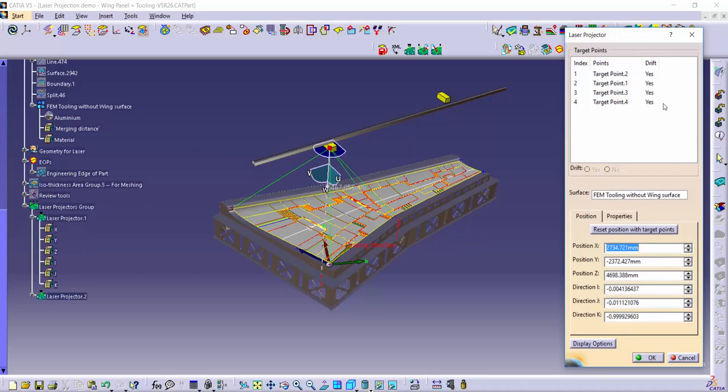When you click on the existing one, you see a couple of calibration points, which are XYZ coordinate points used to define the range of a given laser. After definition of calibration points, you can pick the location of the laser itself, which is again a grid point, and it is further possible to shift the selected laser left or right, or rotate it about the X, Y, and Z axes to put it at the right orientation. When you move it, the positions or the directions will change accordingly.